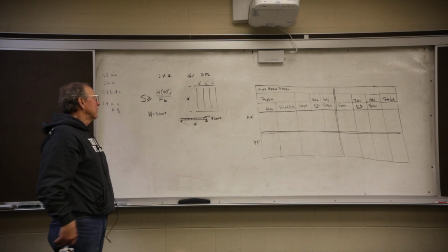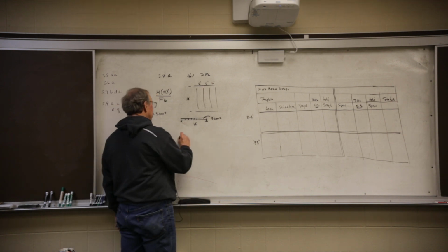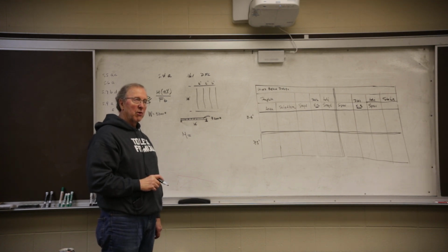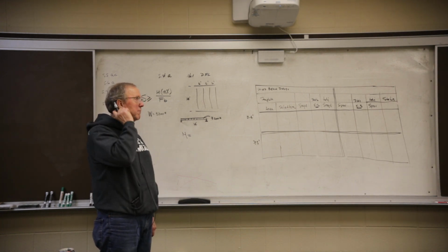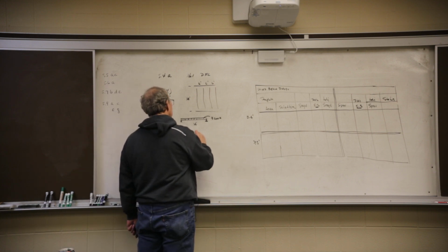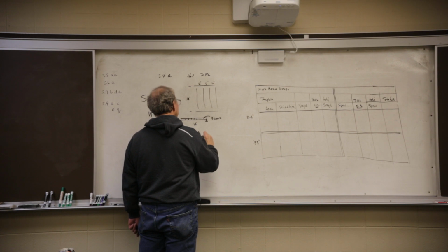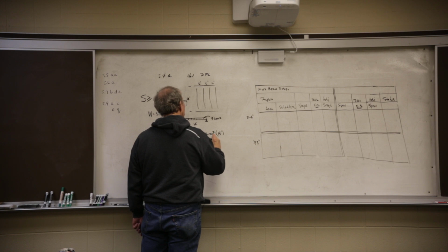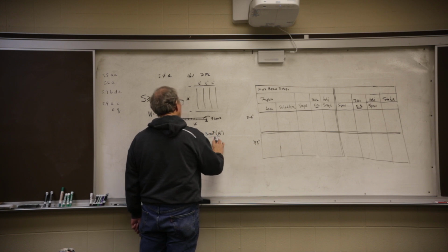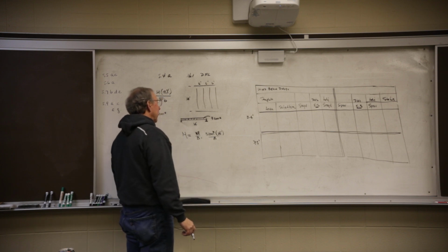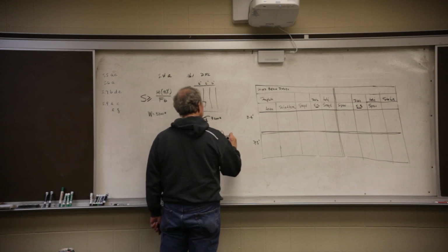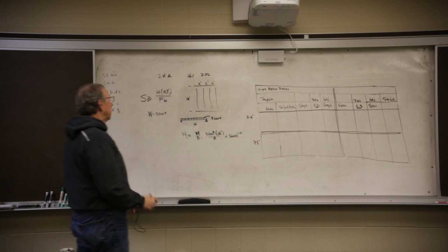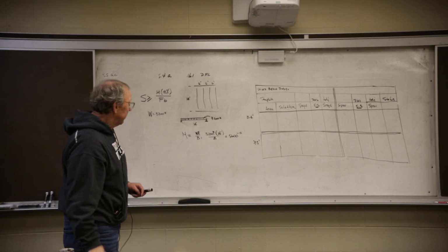So that's the equation. I need the moment. How do I find it? What's the moment of this little sucker? Hopefully by now you realize that's a picture on page 114. And if you look at it, it says big W L over 8. 3,200 times 14 over 8 looks to be 5,600 to me. There's my moment. I'll put him in there. He goes right here.